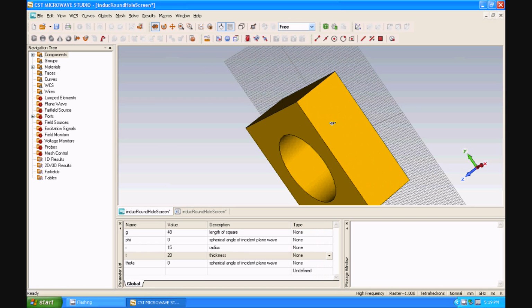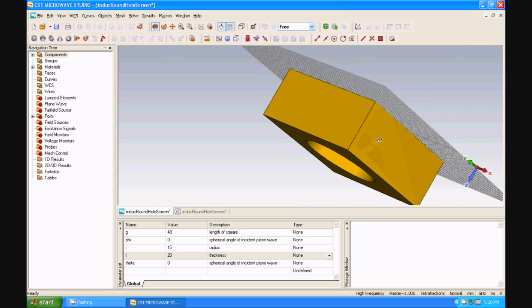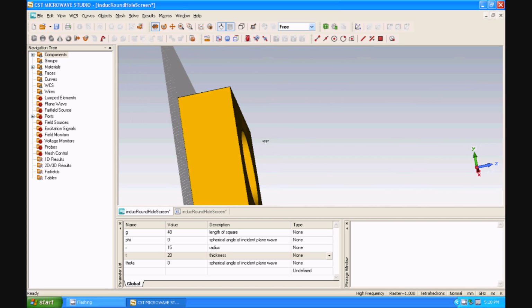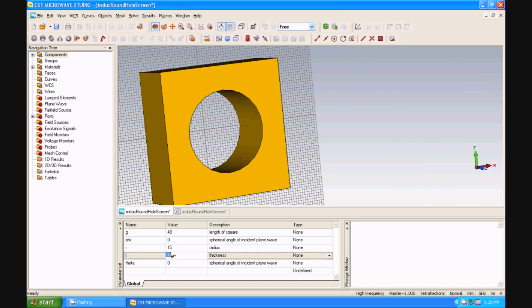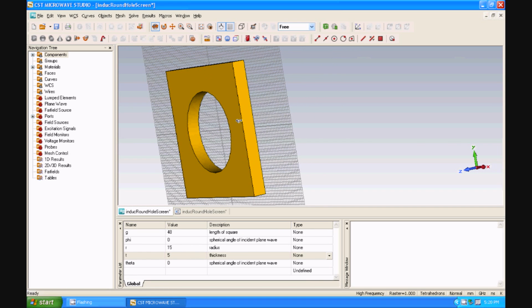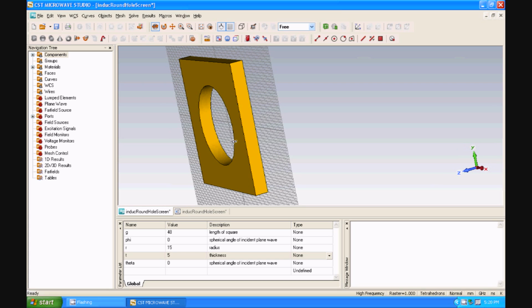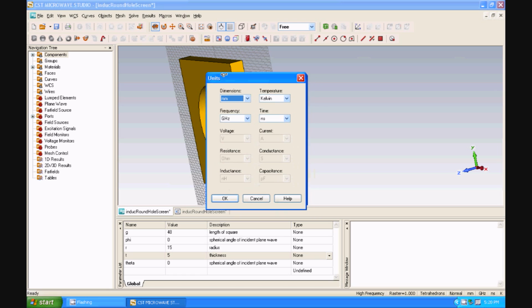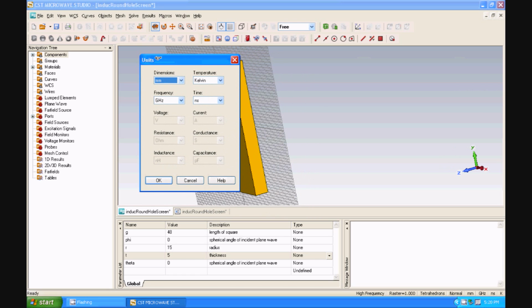Okay, so now that that's been covered, let's move on to step 2, which is setting up the simulation. So the first step is to go and change the units. Now, in my research, we're primarily concerned with the terahertz region, which is infrared light, essentially. And we're also looking at visible light, but let's go with the terahertz region. So change the frequency to terahertz. And because terahertz, if you convert that frequency into wavelength, will be on the order of microns.